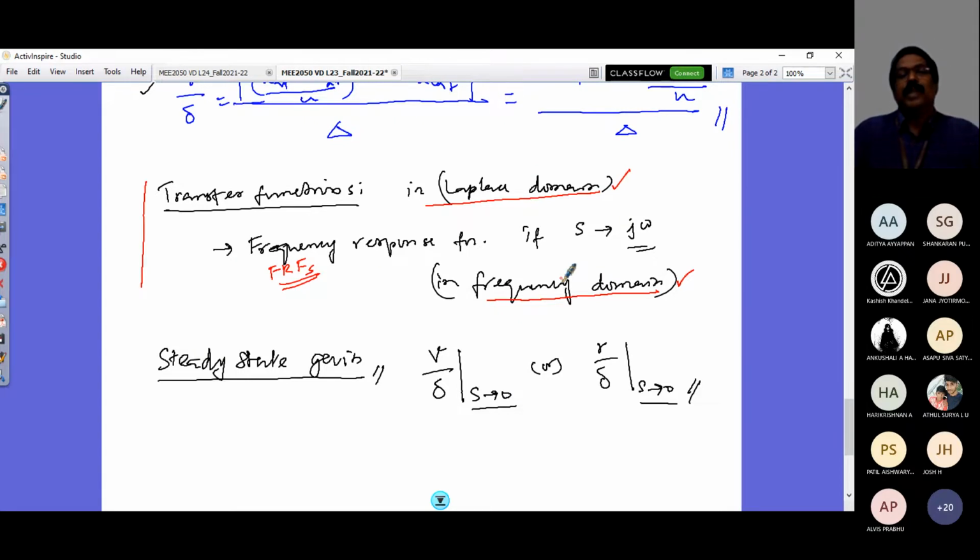So how do I get the impulse response function in my bicycle model? When I drive my vehicle, I give a steer pulse. So I go straight and I give a pulse, and pulse means I just give some steering angle and immediately take it back, the shortest duration. That's the kind of pulse that you can give. When you give that and you get your response, that's what is called the impulse response function. And its Laplace transform is what is called the transfer function, or its Fourier transform is what is called the frequency response function, and so on in mathematics. So keep that aside.